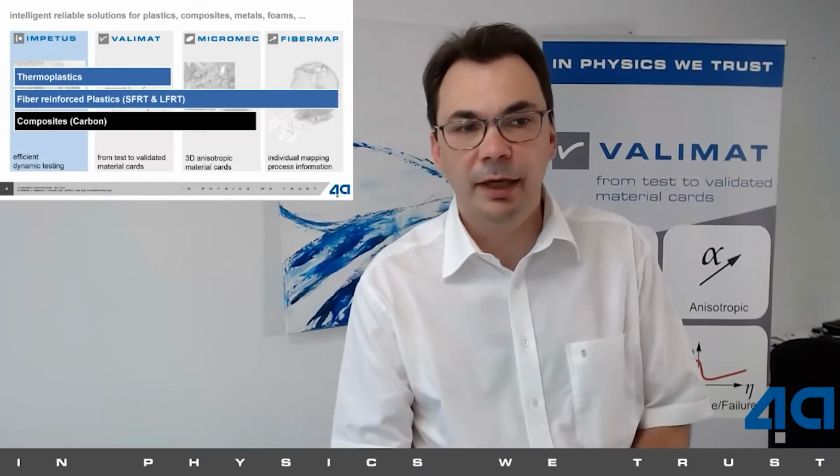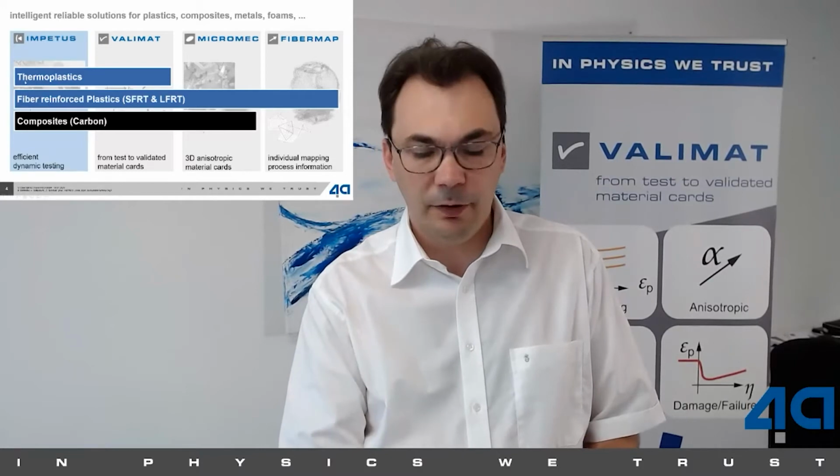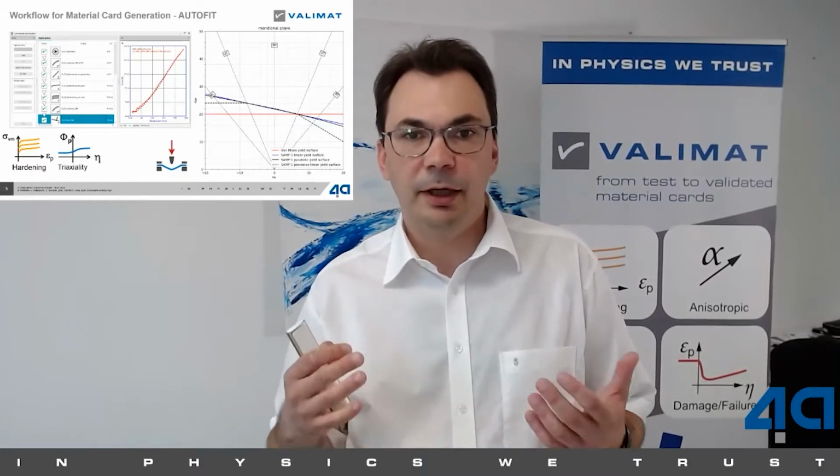So the last days we were talking about our products, and especially we were focusing on the topic of thermoplastic materials and how to generate material cards with AutoFit and what tests are needed for that. We showed you how to make a material model with an easy approach on bending for MAT24, for instance, or for viscoplasticity with von Mises yield surface. Yesterday we focused on a more general yield surface, as you can see here in this slide, and we showed you how this AutoFit could work. I just want to show you some additional information on that shortly.